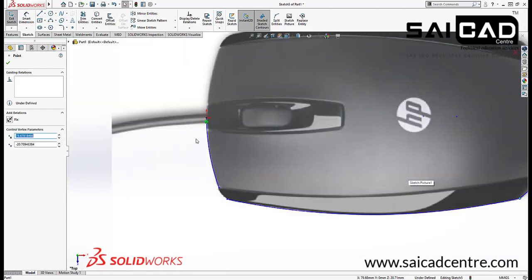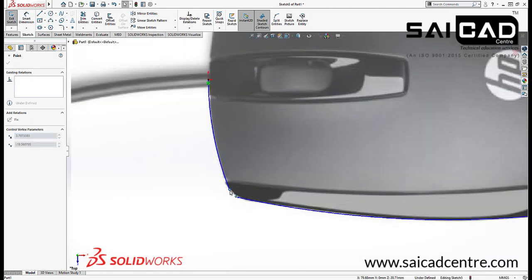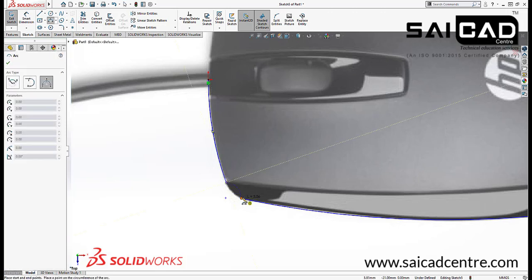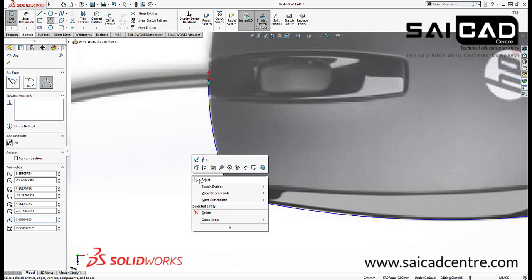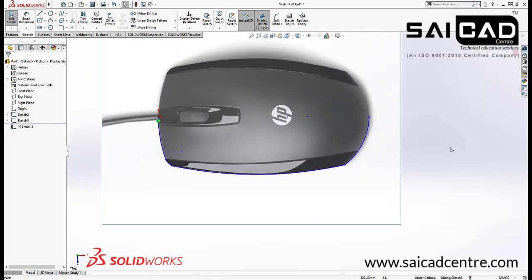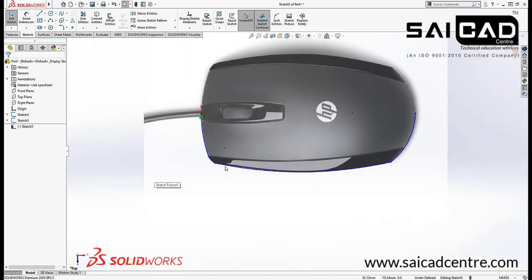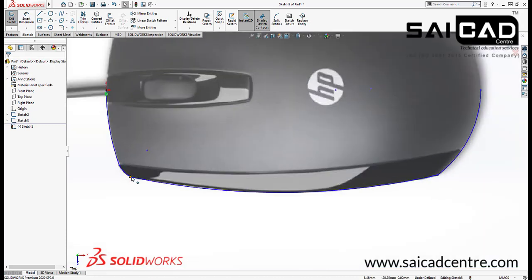So this arc needed to come somewhere here, and this arc needed to come somewhere here, or you can just create this up to this point and use another arc from here like that and create the shape. So in surface we need to create some arcs with some tangencies, otherwise our surface will not be correct.